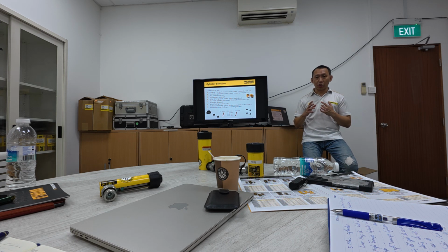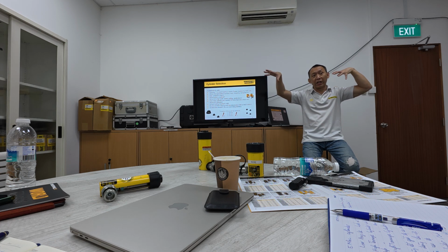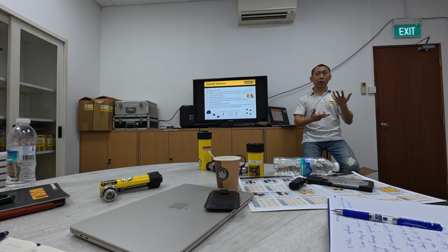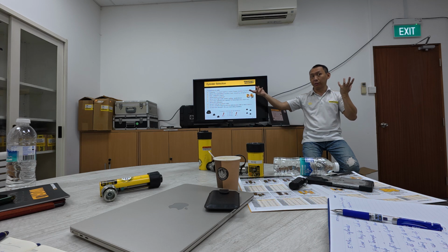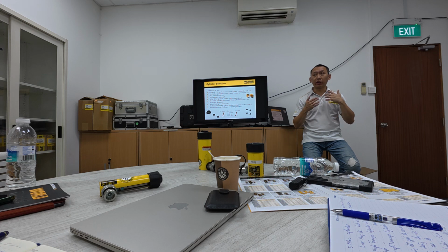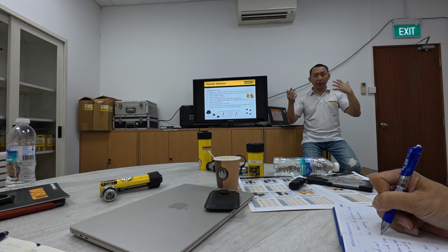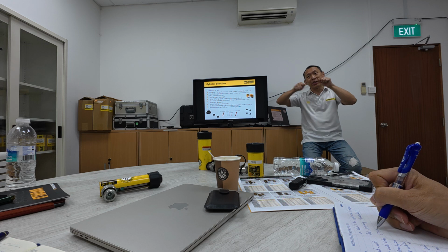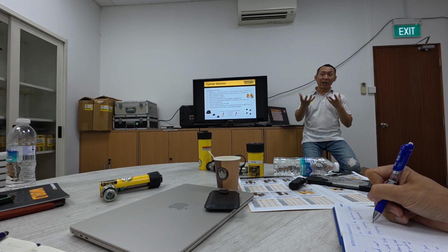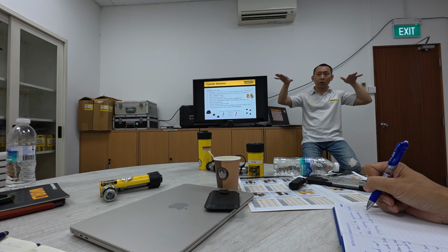And then if you're talking about the frequency, how long, maybe the load lifts and is held there for a long time, then from there we understand they need to hold the load for a long time, and that's where we can probably offer the lock nuts. Or if they want to hold, let's say, just for 1 or 2 hours, they probably don't want a lock nut because it's too troublesome to lock. So we can offer a load holding valve, so that they hold the load for a certain period of time.